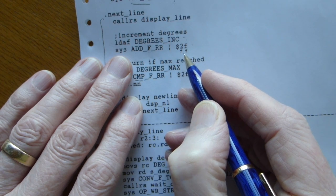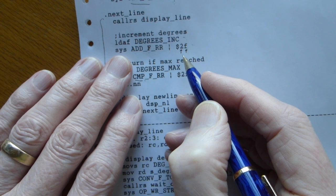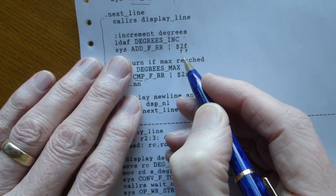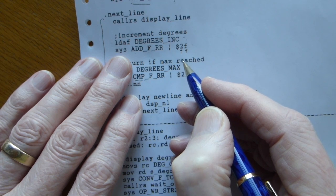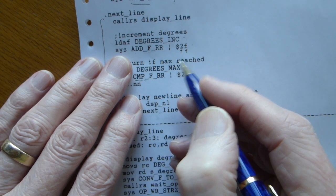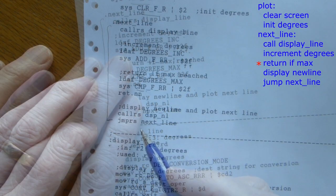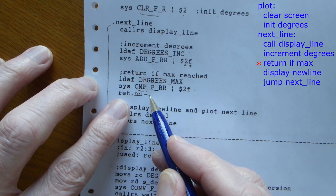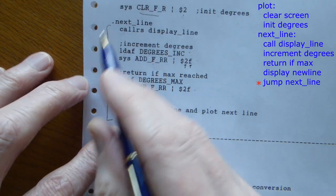Okay, this saves having extra system calls just to handle the accumulator, but note that not all system calls do this. Some treat f as illegal, and others treat it as an extra control function. We'll see one later on. If in doubt, refer to the instruction set manual. The routine then either returns if finished, or displays a new line and loops back to the next line.